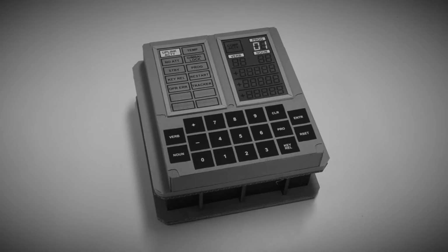The DSKY shows the values the computer intends to use. These can be accepted or changed by the astronauts. Pressing proceed allows the program to go on. The proceed key is also used to confirm engine ignitions and for powering down the AGC. The condition indicators are directly controlled by the software and inform about the current status of the computer as well as warnings or errors. Uplink activity lights up when the AGC is remotely controlled by ground controllers in Houston.